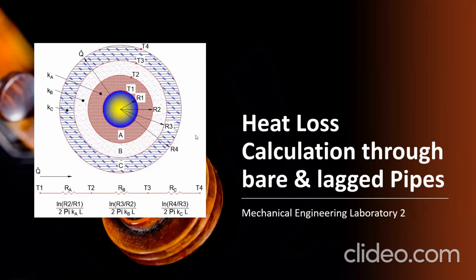So this is heat loss calculation through bare and lagged pipe under the Mechanical Engineering Laboratory 2. The title is heat loss calculation, not testing. But in testing, of course, this is also the principle, you use the formulas. You can see in the figure this composite pipe, with three layers. This is the thickness of the pipe, insulation, and either cladding or other insulation. So this is the equivalent electrical diagram.